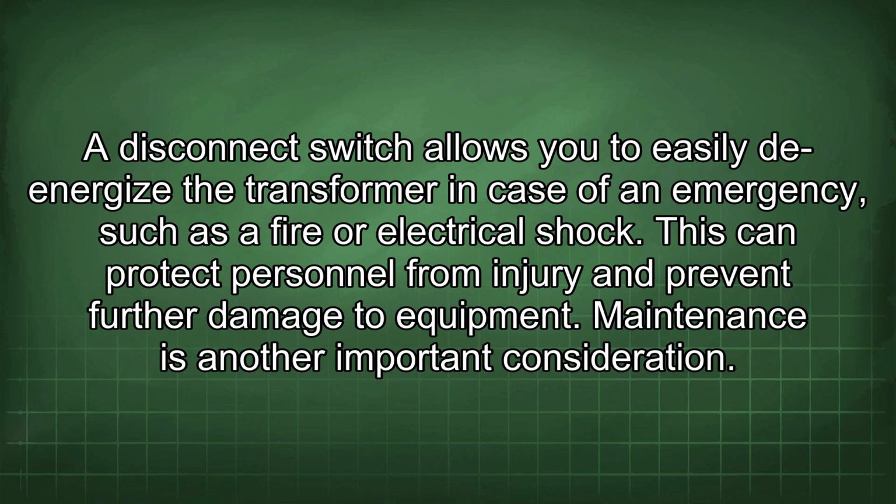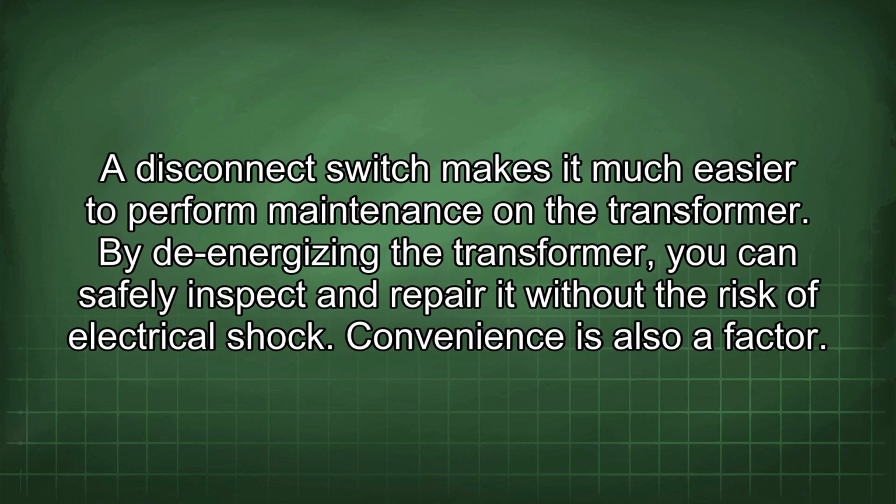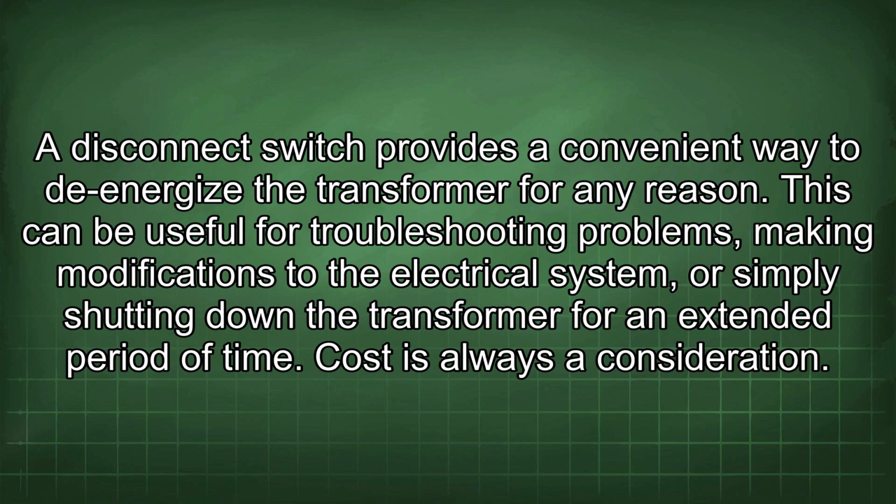Maintenance is another important consideration. A disconnect switch makes it much easier to perform maintenance on the transformer. By de-energizing the transformer, you can safely inspect and repair it without the risk of electrical shock. Convenience is also a factor. A disconnect switch provides a convenient way to de-energize the transformer for any reason. This can be useful for troubleshooting problems, making modifications to the electrical system, or simply shutting down the transformer for an extended period of time.